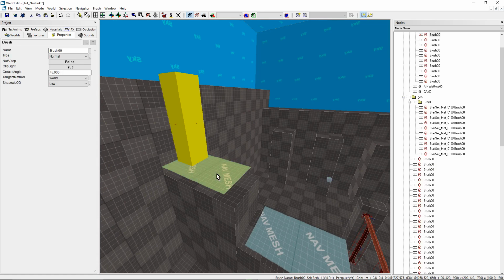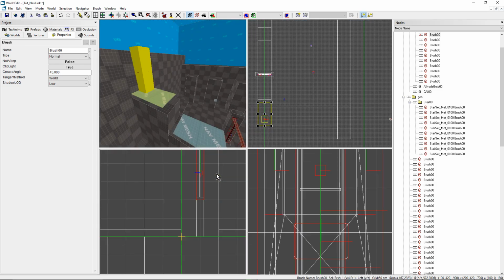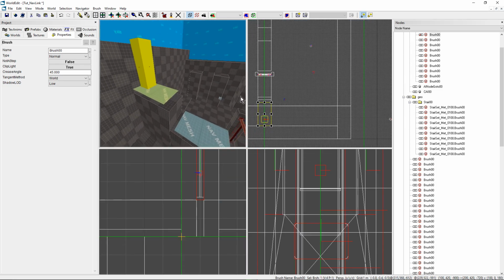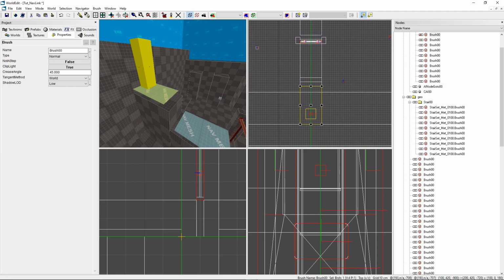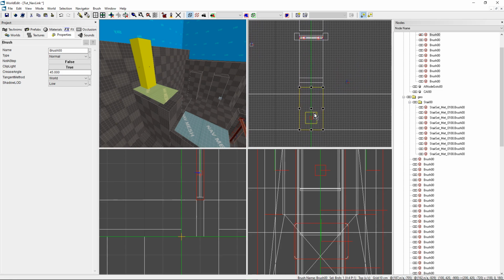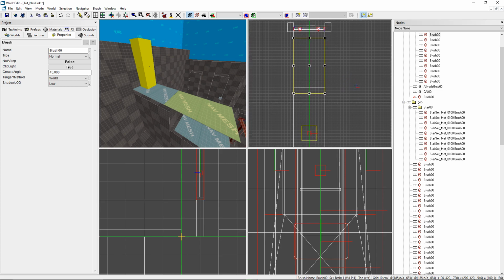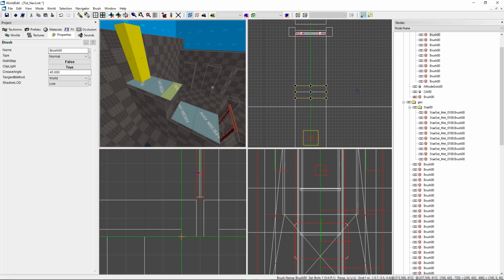Okay, so let's get started. The best way to create a Navmesh link is to go in the top view into clone, like drag and clone an already existing mesh or plane. So I do the first one like this, and then put that smaller.